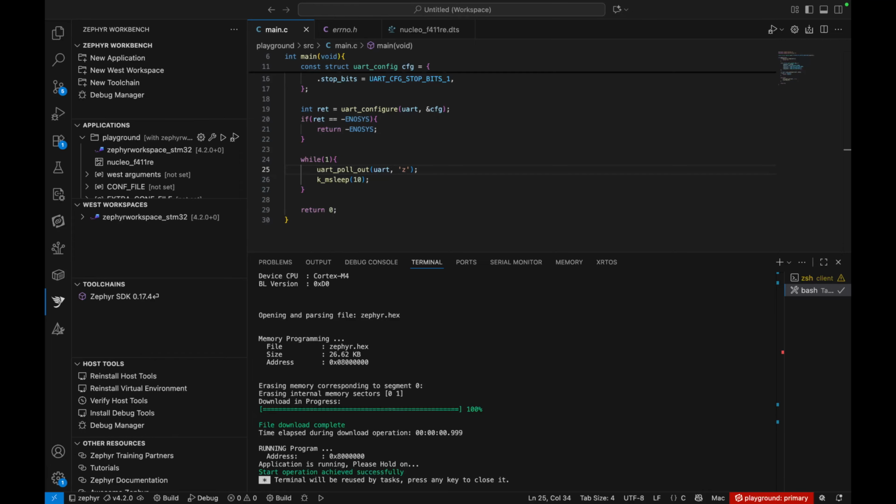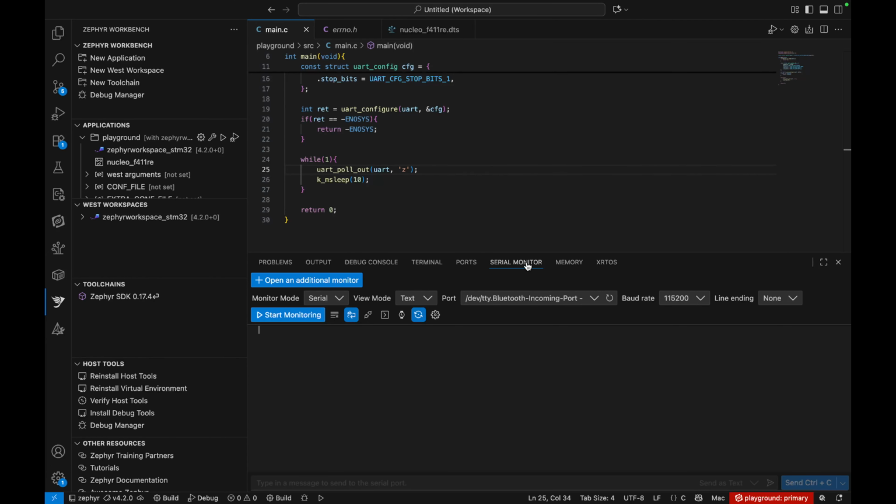How do we read this information that is coming? There are programs called terminal emulators that you can use. Thankfully, VS Code or the plugin already comes with a terminal emulator. So if you click on this serial monitor here, it's actually a terminal emulator. Now, it has to establish a connection to the microcontroller, and the port, I have done this so I know which particular port is the virtual COM port, this one. And then you have to choose the baud rate.